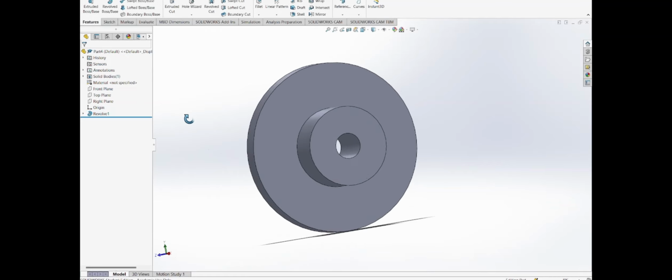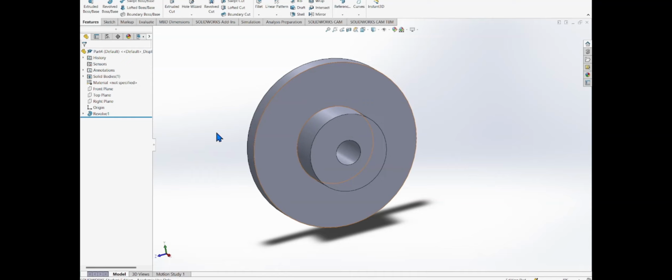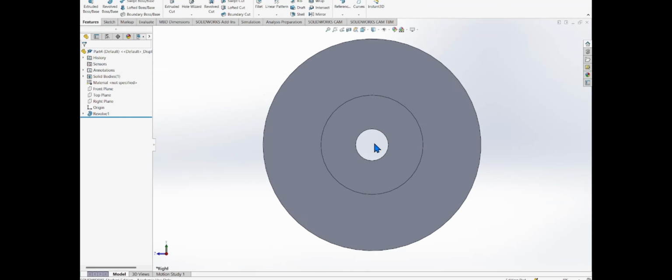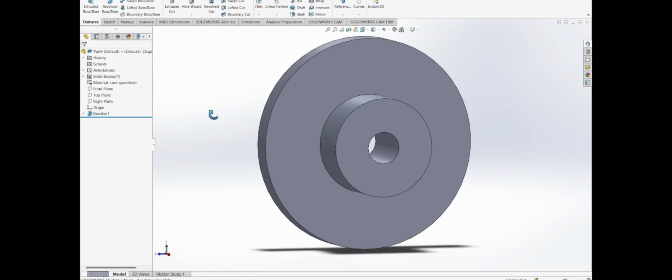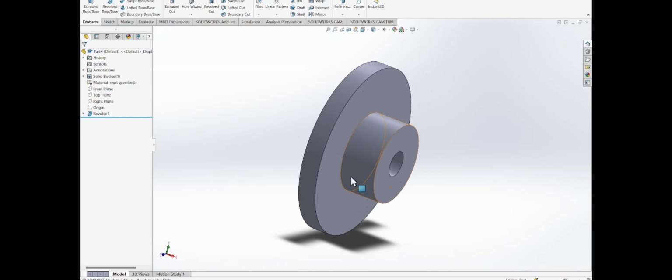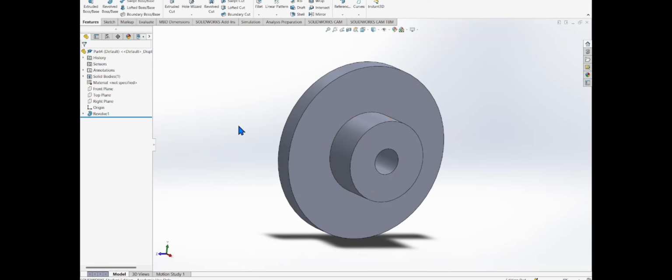There you go. Because traditionally, if you do it the other way around, like doing this top view right here, you do circles right here. You got one circle, you got two circles, you got three circles. However, if you want a quick way to do a 360 revolve, it'll be this right here, to do it two dimensionally quicker and not to do a 360 right here. So either way, vice versa. But again, you have to practice this every once in a while because you have to get used to the revolving. If there is a part that's given to you that has a two-dimensional profile, you work with that one right away, rather than just doing the traditional way.